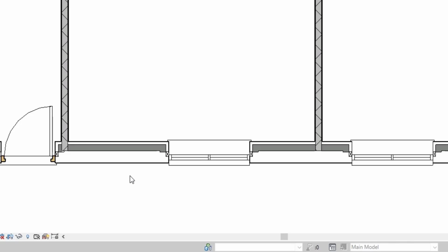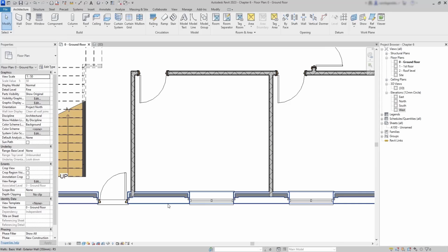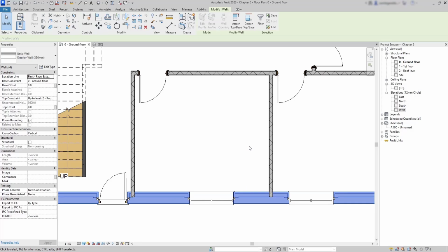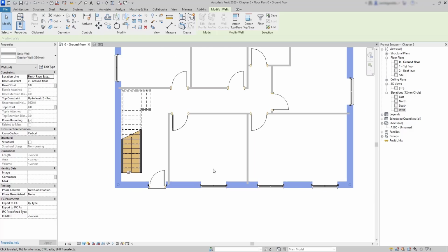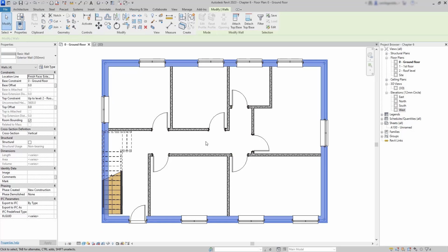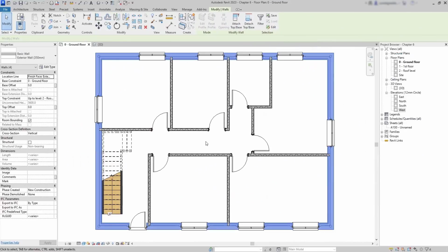First, to select all the exterior walls, I pick up one, right-click, select all instances, and then choose Entire Project. In this case, a visible view would also work. Now, if you remember, I can hit the spacebar to flip the wall to the other side, but it's actually changing the position. And this is because I'm flipping according to the position of the location line.